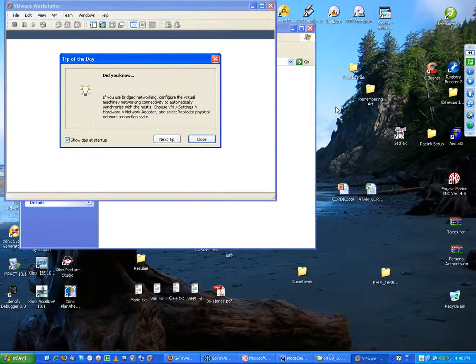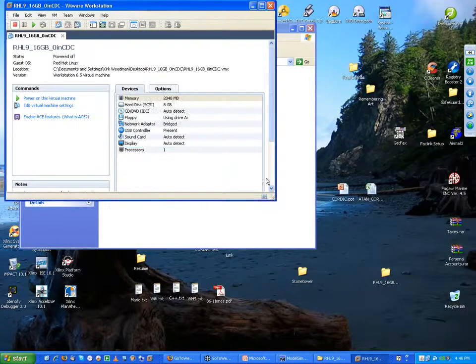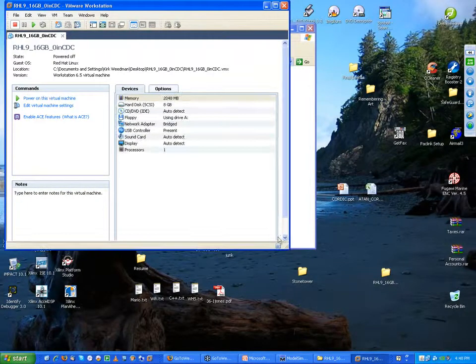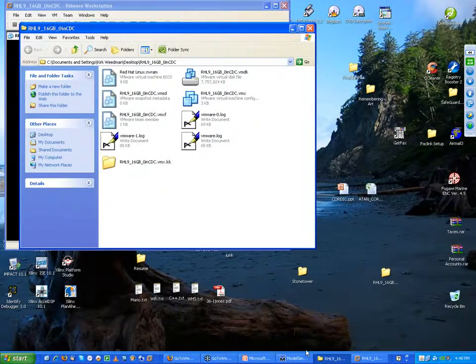Okay, are there any questions during this time, or did any of this make sense? Yeah. As a first pass quality check on this, could you take the output data, run it through a Fourier transform, with as much resolution as you need, and then look for the spurs that people were talking about that might be there as a result of a lack of round off? Is that kind of the first step validation on something like this?